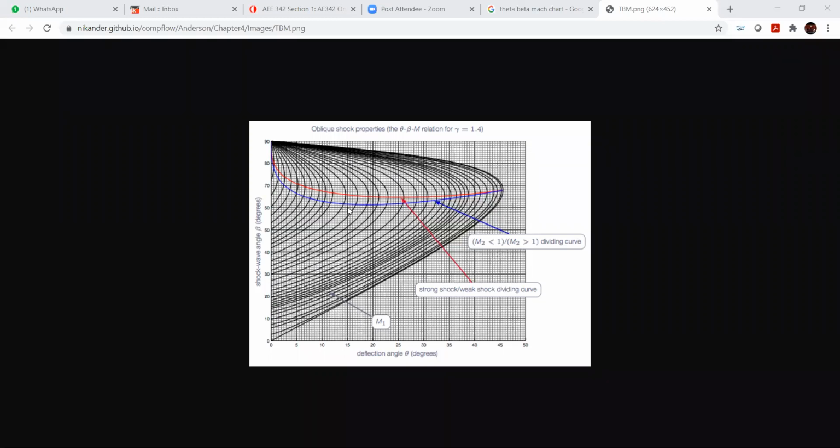As the Mach number increases, as you go to higher and higher supersonic speeds, you go towards the right in this chart. So let's say if this is for Mach 2, the next one could be for Mach 2.2, the next for Mach 2.4. From left to right, Mach number increases. So each black curve is a solution of that equation for a given flight Mach number.